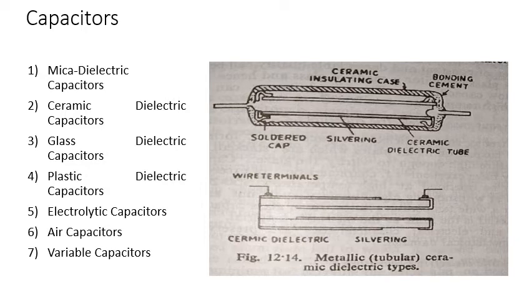Then electrolytic capacitors. The characteristic of this type of capacitor is their low volume for large capacitances, especially at low working voltage. These are suitable for use in high energy pulse storage applications, and the normal types are made of plain foils of aluminum. Sprayed gauze foils or etched foils can be used to obtain large surface area and hence higher capacitance. The periodic reforming of electrolytic capacitors which are stored for a long time is essential.